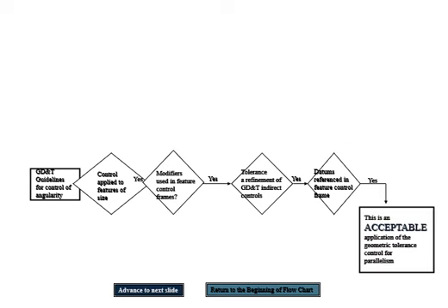And if your datum reference is yes, then that's an acceptable application. So to make it simple, in order for us to deal with the angularity, you're going to take a look at your feature of size. Then you're going to look at your MMC or LMC. Then you're going to look at your datum reference. This is just a geometric control, dimensioning and tolerancing.